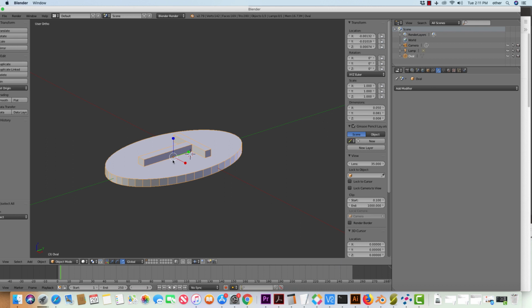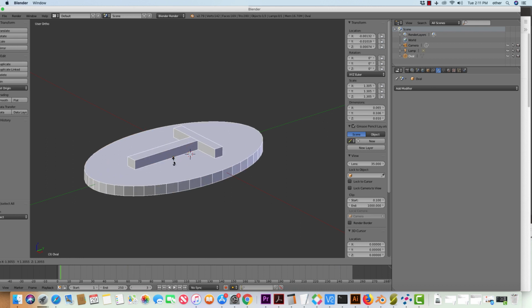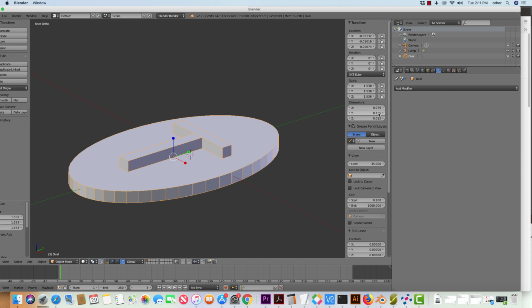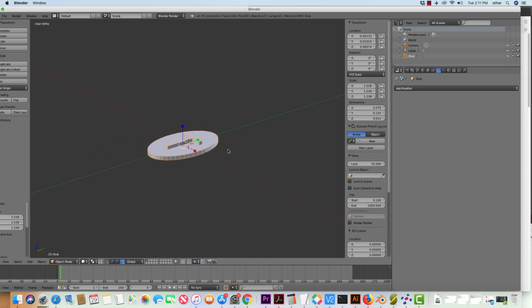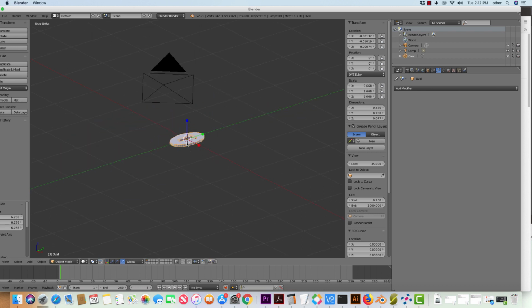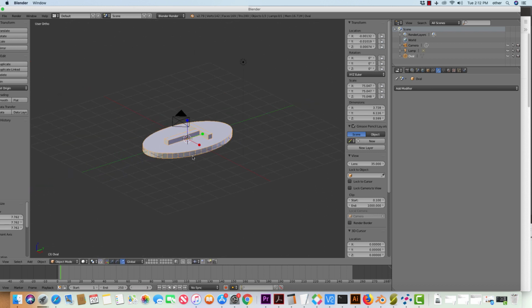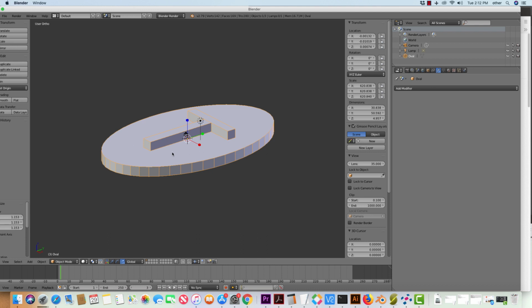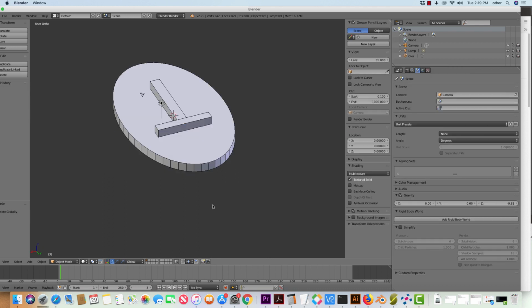And the white circle, go ahead and click on it, and as you're doing it, make sure you're watching the Y number. So I'm just making this bigger. See how small it is? Let's read it. So right there is 50 millimeters. Big difference, right? So that's scaling it to real world size. And now we can drill a hole in it.